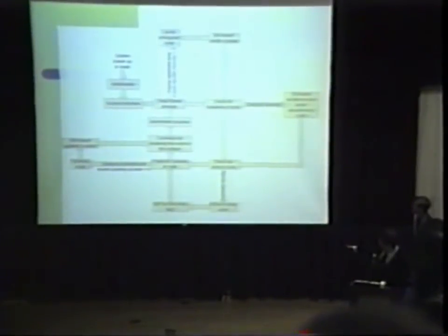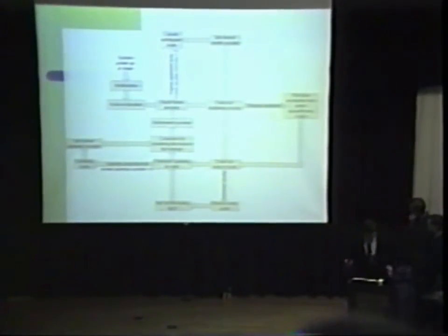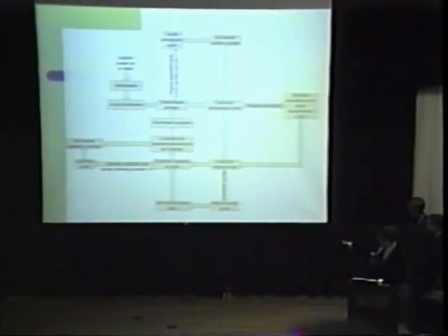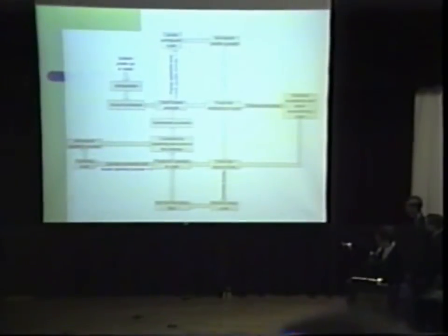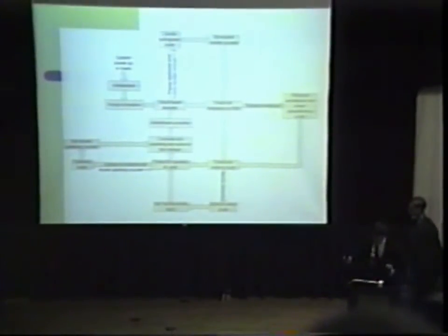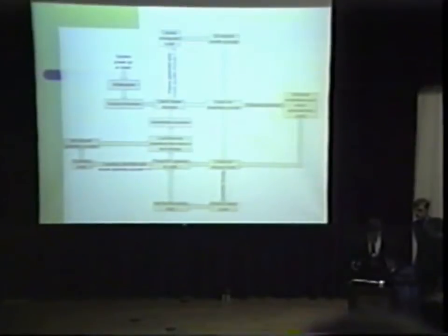Over here, this is where it checks for the ramp. Our ramp code, we have some slight difficulties with our ramp code, which I'll get into later. But the way we wanted to set up the code was so that it would drive to the ramp and then go up it, set a flag, and then change the controller so that the controller would now be keeping it straight on the ramp.